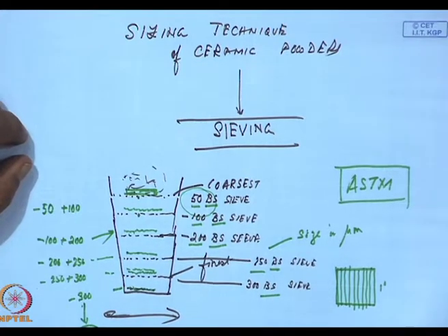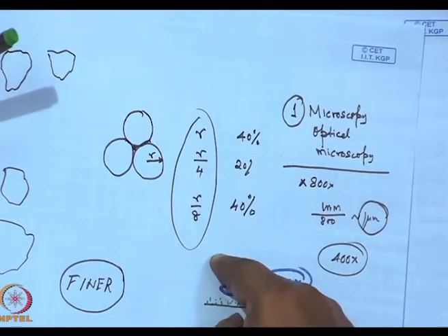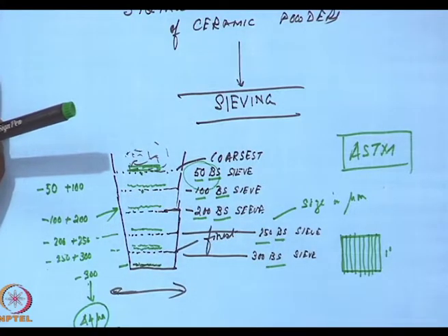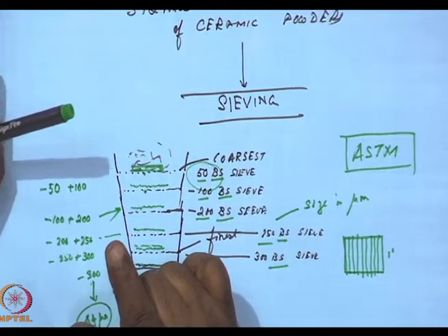So, when in the ceramic industry they want to make, say, a cup, the cup from which you drink tea, they want to ensure that the powders are properly distributed. As I had said, one should have this ratio of powders. What they would do is take the raw materials, grind them very well, and take these size fractions and mix them properly so that maximum packing occurs.